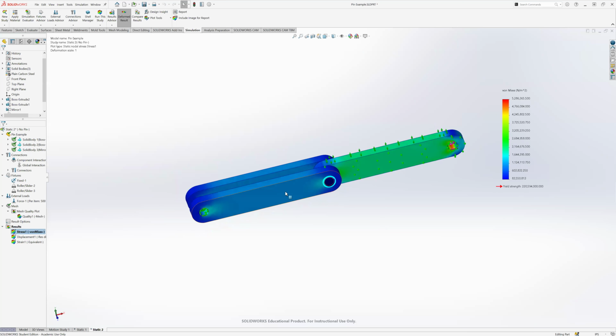So whenever you're using simulations, there are usually 3 things that you want to have correspond when you're designing a product or trying to make sure your product or device is going to actually work as intended. You obviously want to do hand calculations. You also want to do simulations, and if possible, you want to do physical testing as well. And between all 3, you want to get values from those different analysis methods around the same amount. Again, they're not going to be identical, because hand calculations versus FEA versus physical testing are going to be different. But if they're within a small percentage of each other, then you know that you've analyzed your system correctly. So that's something you always want to do.